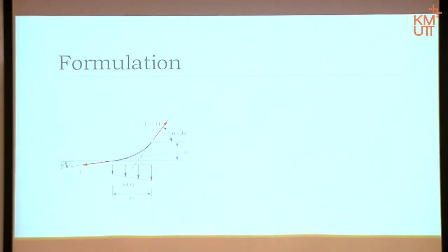Now, we don't know the force, but we can put in symbols for the forces and the angles. So maybe it's time to start doing something about the equilibrium. Don't forget our bridge doesn't move. Our bridge should stay there, so this small element has to be in equilibrium as well. If it is in equilibrium, sigma Fx must be 0.